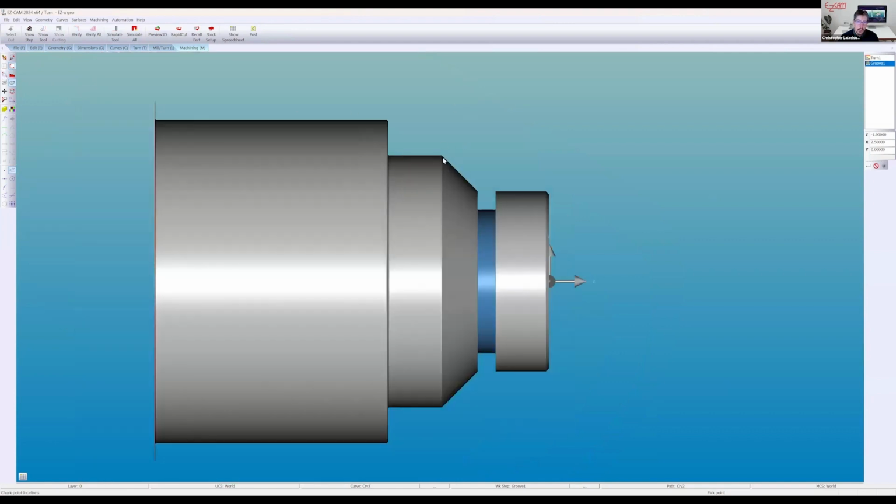So that's how you would work with geometry. It would work the same way as in the bore, but remember, you have to create the rapid move on your curve path. So if we go here, rapid is an option. You select a clear point, go into the bore, select another clear point, create your groove, and then you've got to add another clear point to make sure you have the proper exit.